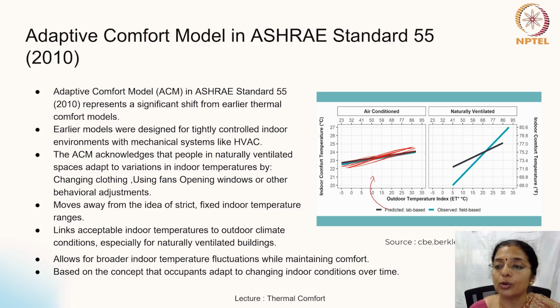People also wanted that. But in naturally ventilated buildings, it did not match the predicted values. The values which were predicted would make people comfortable did not match with the actual values that people said made them feel comfortable.